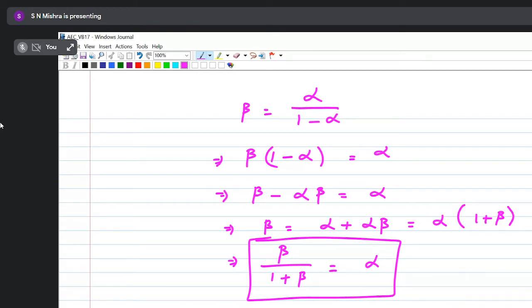It is a low pass filter. If the frequency component is higher than the cutoff frequency, it will be blocked. Similarly, in case of high pass filters, it will pass the frequencies higher than the cutoff frequency, and frequency components lower than the cutoff frequency will be blocked. Any doubt? Here we are talking about optical filters.